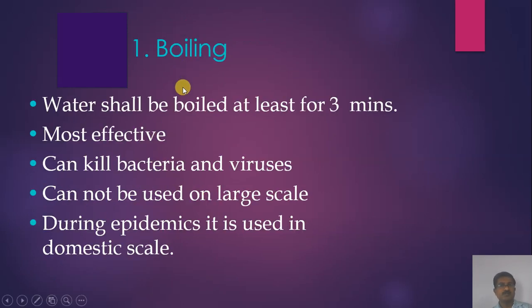The first one is boiling. Water shall be boiled for at least 3 minutes. It is the most effective method. It can kill bacteria and viruses. It cannot be used on a large scale. During epidemics, it is used on a domestic scale.